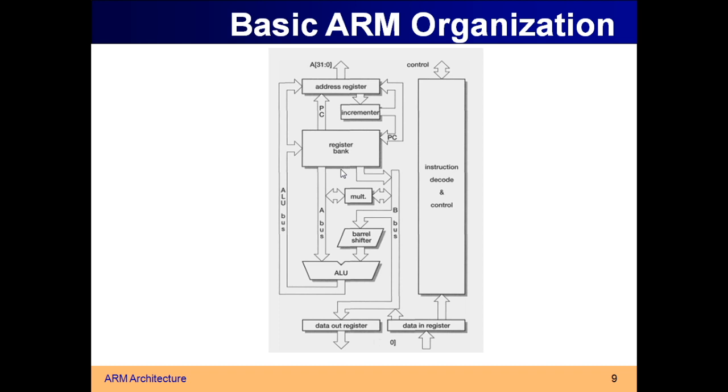If you want to send a single bit of data between two blocks, you use something known as a signal. If you want to send multiple data bits between two blocks, you should go for a bus. So a bus is a collection of signals through which you can transfer multiple bits of data or instruction.